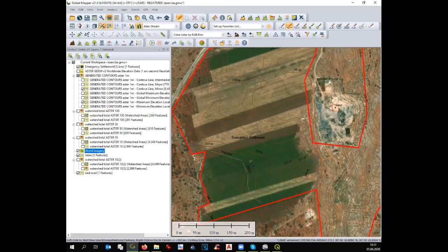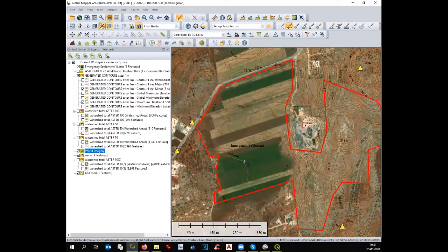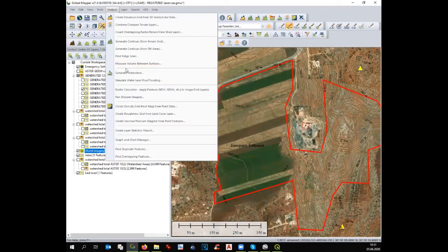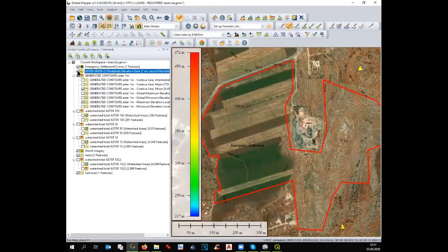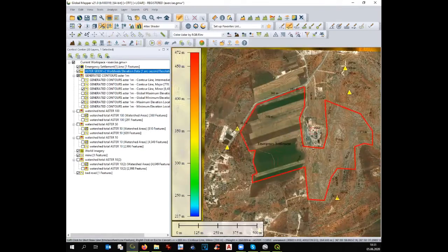So it's a natural drain, and there is a way to find the, how do you say it in English, the ridge line, the ridge. You know, the ridge is like the peak. Let's do that to see the best place to put the road. Again, we open our digital terrain model. We'll zoom out a little bit.